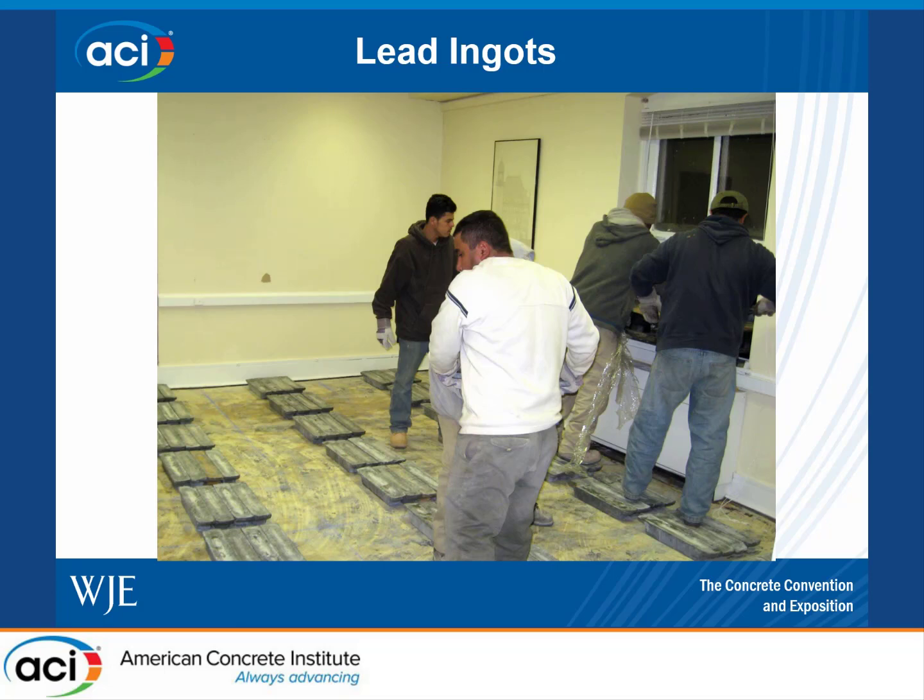Here's just a quick photo showing some lead ingots used on a small interior load test where we needed line loads. This is load stage 1 of a line load over, I believe this was a joist floor system that we were looking at, just putting a line load right over the stems. You can use something like this in a small enclosed area where large water tanks or hydraulics may not be a good option.